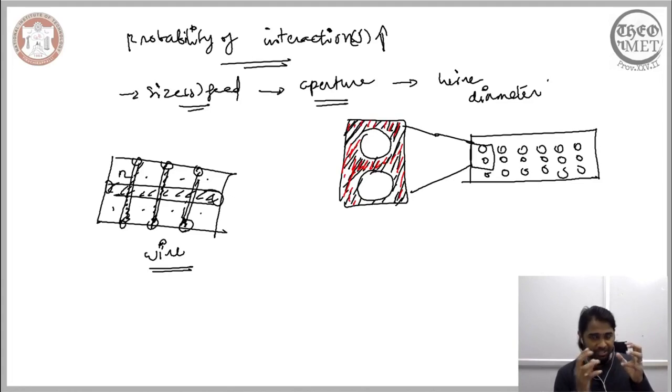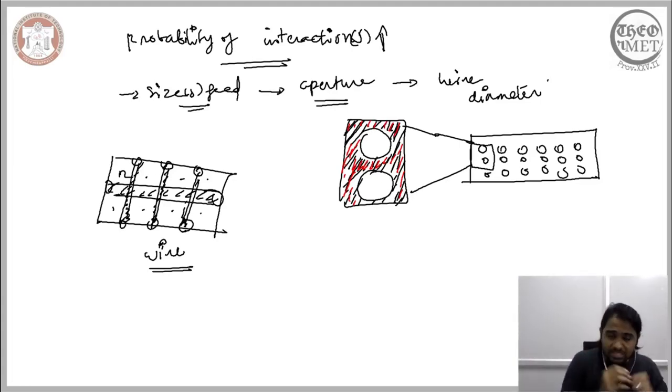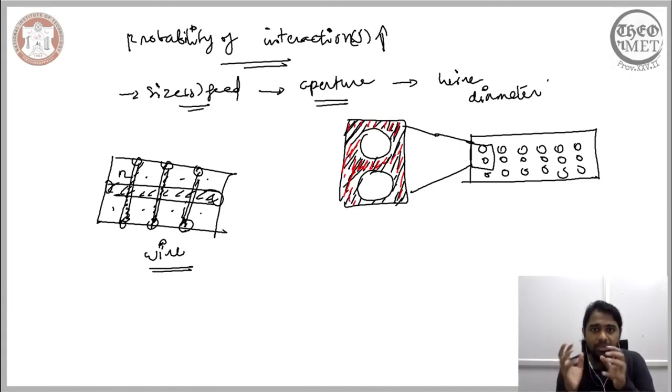Now when you consider both these interactions, the role of the size of the particles is quite pivotal. Depending on their size, these particles can either take up a position on the surface, or a position above the surface, found above the underlying particles. So the interaction between the particles themselves depends on their sizes, and the interaction between the particle and the screening surface depends on both the size of the particles and the aperture. This interaction between the particles and the aperture, that is the opening, can be described in a definitive manner, based on the size of the aperture and the size of the particles.